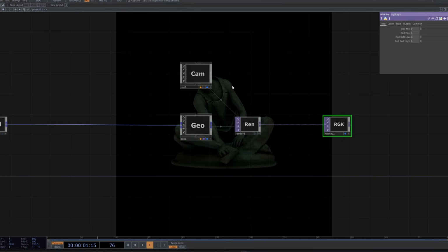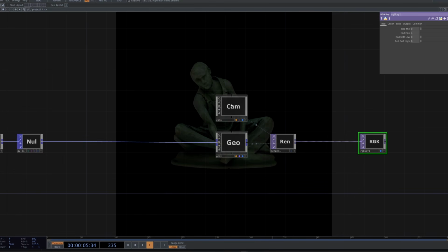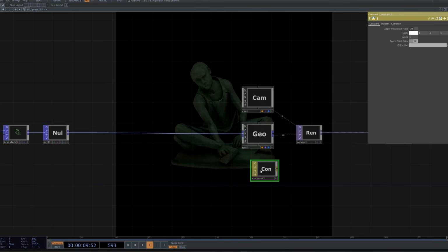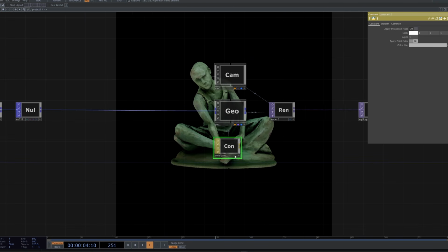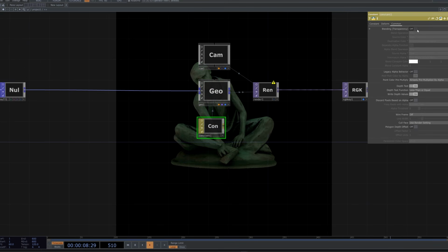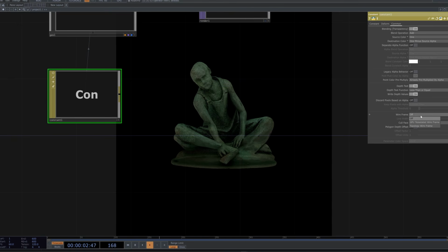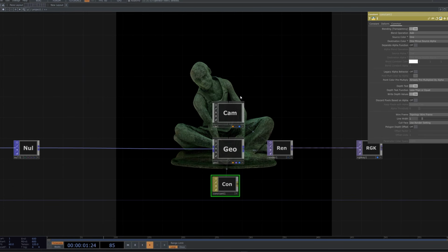So we do have our model loaded now, but we can already see it lacks light. So I'm going to use a constant material, drag and drop it on my material, and now I have my 3D model. I'm going to lower down the alpha a bit, and in common activate the transparency. So right now I have something interesting, but I want it to be wireframe. So I'm going to go for topology wireframe and with 1. And we have something already quite interesting.